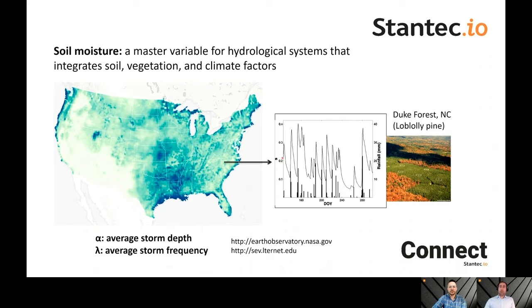And this is essential because if we look at soil moisture as shown with the data here, it decreases in time because of evapotranspiration, plants pumping water out of the land surface, and then it increases in time because of rainfall events. As we can see, the rainfall is quite sporadic, and so consequently so is the soil moisture. So if we do have a statistical overfitting, it's likely that we could find ourselves in the wrong trajectory. But if we capture the statistics, we're likely to capture an average as reasonable, as I will show, for predicting what that runoff amount is.